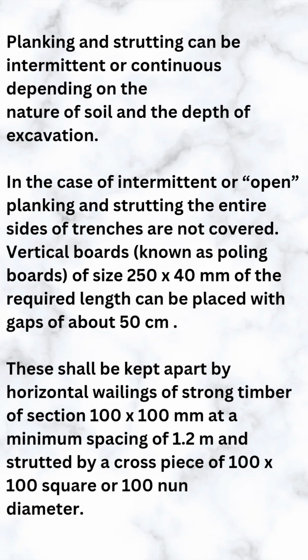But if the soil is loose and the excavation is deeper, in that situation we need to provide certain shoring, or we can say support, because it may fall. Whatever soil you are going to excavate, part of the soil can fall back into that particular region, and we need to take care of that. Then planking and strutting can be intermittent or continuous depending upon the nature of soil and the depth of excavation.